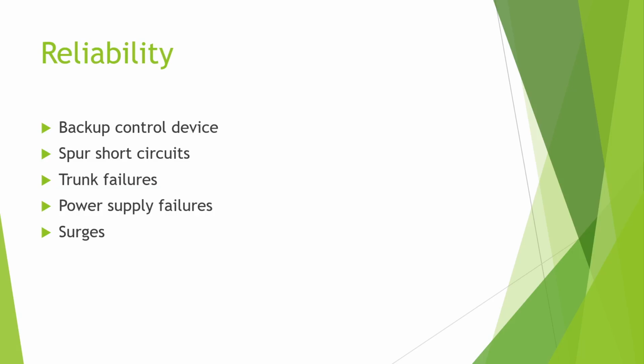Oh, physically protect it, right? I don't want to be able to have an axe or a wheel or something hit this wire. So we could run it in conduit, armored cable, something along those lines. Yeah, this is not like, oh, we're going to do something electrically fancy here. No, this is like, put it in armor, protect the thing, right?